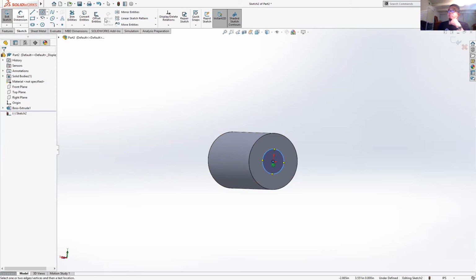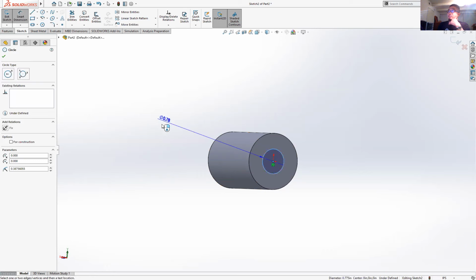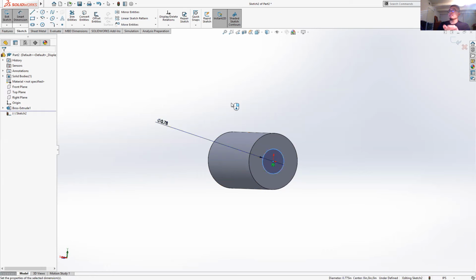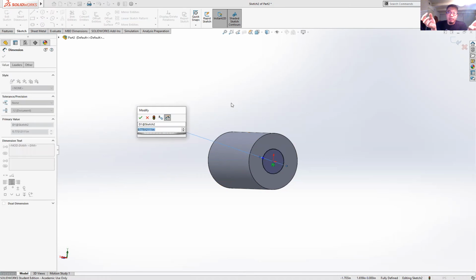And then I'm going to go to smart dimension, and I'm going to add a circle dimension. So then I click here, okay? And so let's say I have a shaft that's 6 millimeters. So watch this, I can do 6 millimeters. And then I can do plus. I can actually put equations and different units, and it'll know how to scale everything. Solidworks is very nice that way. And the 3D printer, let's say 3D prints holes a little smaller than normal. So if I want to make sure that it can slide in, I might add 8 thousandths. So 0.008 inches. I might add 15 thousandths depending on the slip. So with your 3D printer, you guys can play with those different tolerances, right?